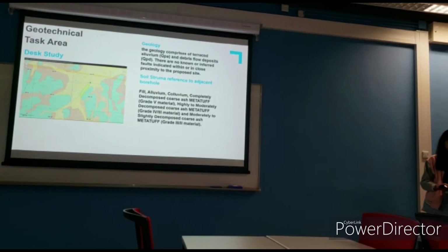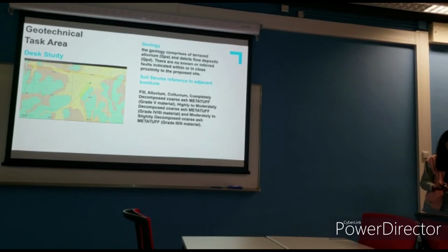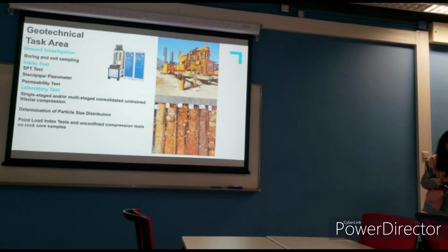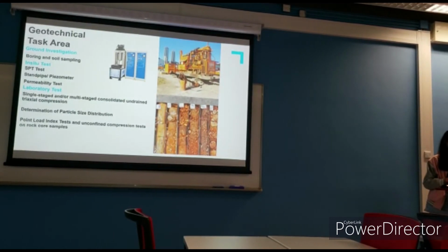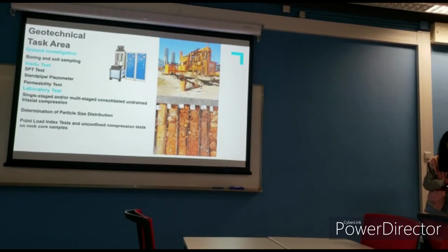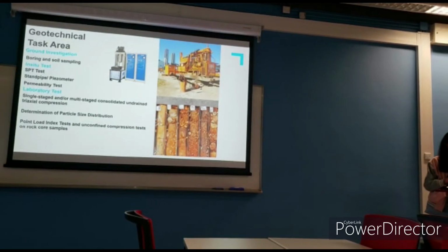We can see that all the materials are sandy in nature. For more precise design purposes, it is recommended to carry out ground investigation by boring test. A vertical borehole should be sunk into the proposed site to obtain soil samples. Also, in situ tests such as standard penetration tests should be carried out to obtain the soil layers, in order to estimate the relative soil density and soil strength for design purposes.